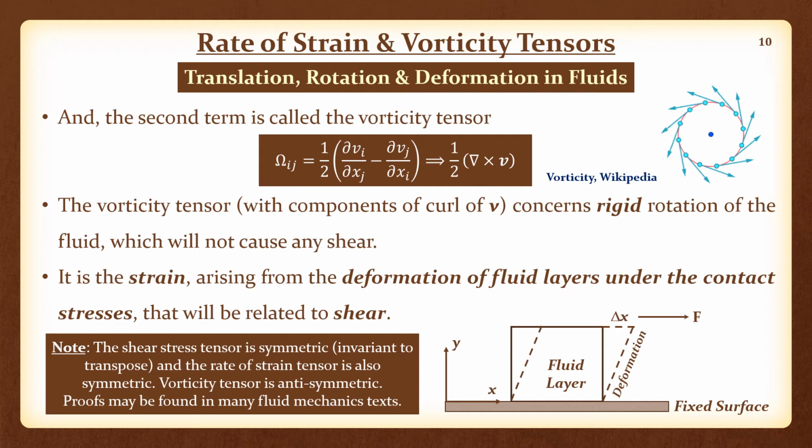In other words, if the fluid is flowing in the x direction, and by virtue of friction, molecular momentum is transported to the y direction, that would be captured as tau yx.